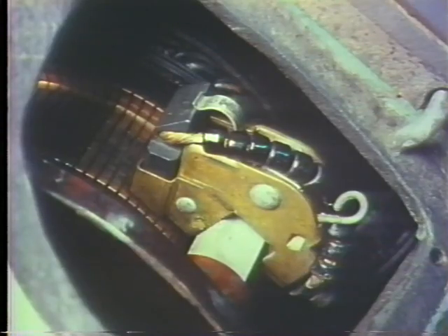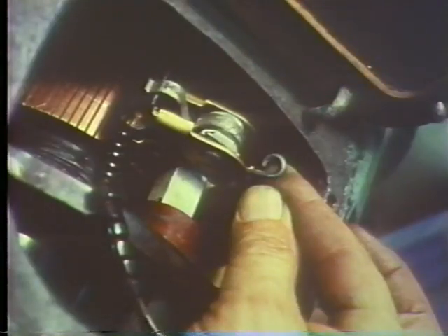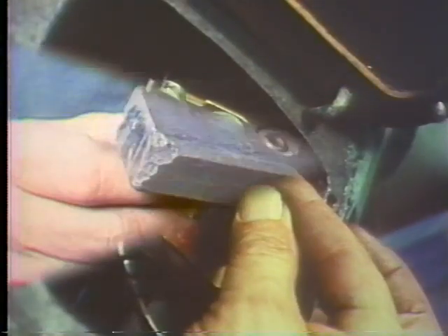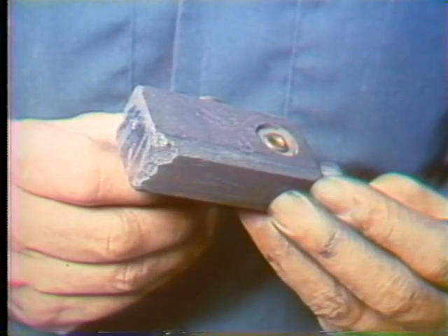Brushes can hang up in their holders and break contact with the commutator, or the pigtail can bind on the holder. That will cause the brush to break contact too. You've also got a problem if the brush doesn't make full contact with the commutator. If the brush tension device is set wrong, there'll be trouble. Broken, cracked, or chipped brushes will also give you headaches.